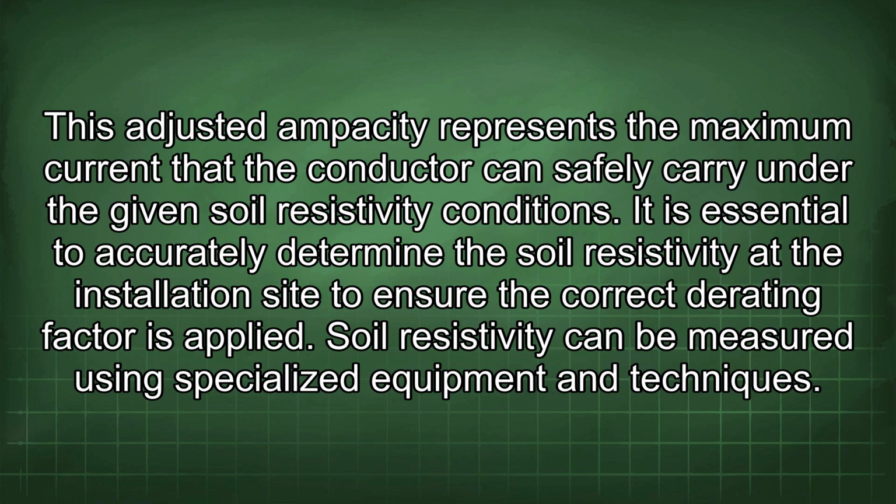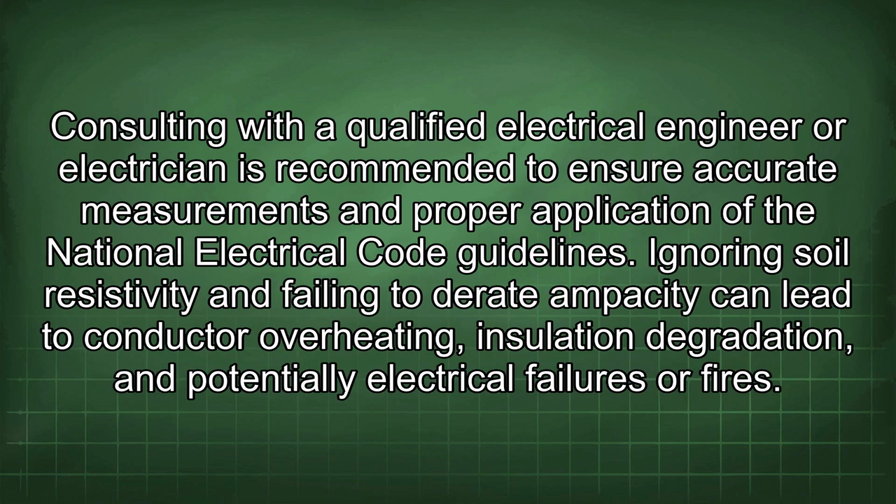It is essential to accurately determine the soil resistivity at the installation site to ensure the correct derating factor is applied. Soil resistivity can be measured using specialized equipment and techniques. Consulting with a qualified electrical engineer or electrician is recommended to ensure accurate measurements and proper application of the National Electrical Code guidelines.